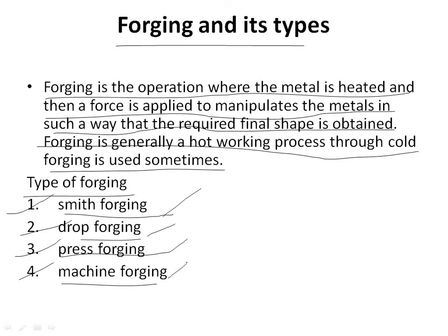The upset forging cycle starts with the movable die sliding against the stationary die to grip the stock. The two dies, when in closed position, form the necessary die cavity. Then the heading tool advances against the stock and upsets it to completely fill the die cavity. Having completed the upsetting, the heading tool moves back to its original position. Then the movable gripper die releases the stock by sliding backward.